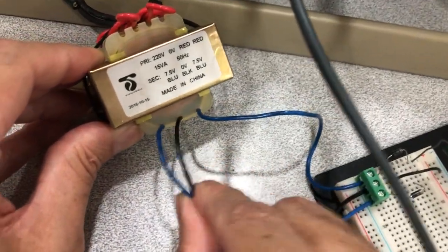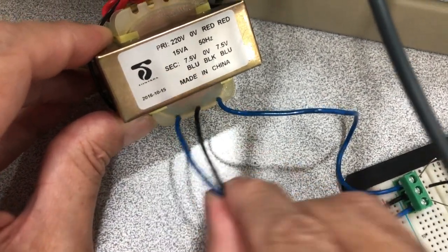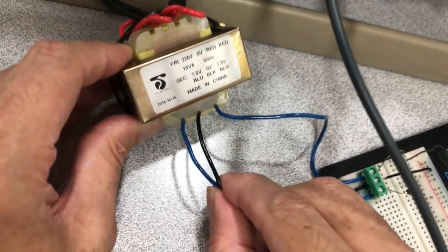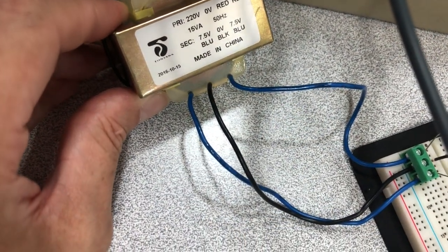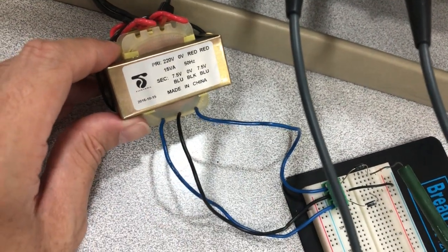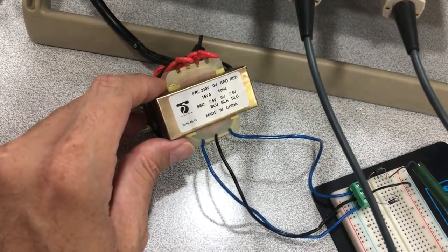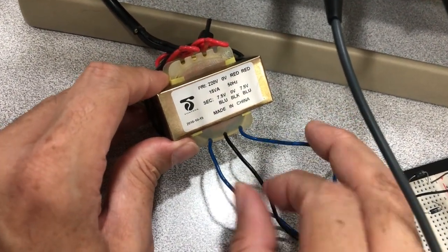Now out of half of the secondary, here they wrote SEC meaning secondary, I have 7.5 volt times 1 amp is 7.5 volt amps. So volt amps is like power, voltage times current. Now why in AC we use volt amperes is because there may be some power factor, and there is apparent power and real power. We won't get into electric circuits here.